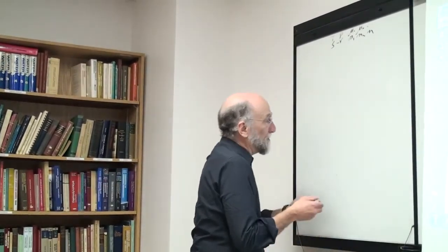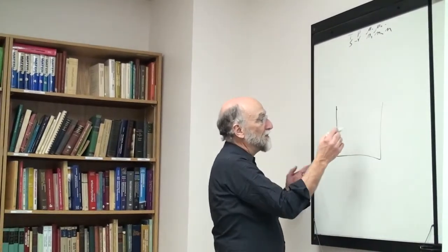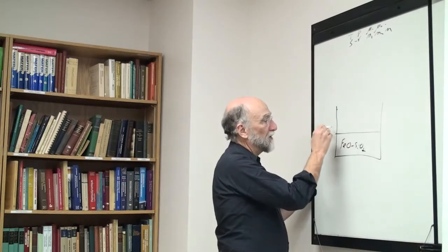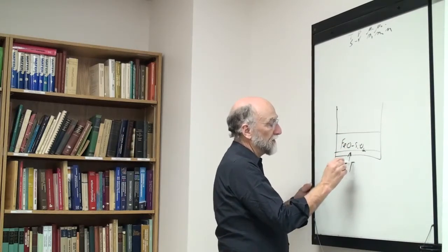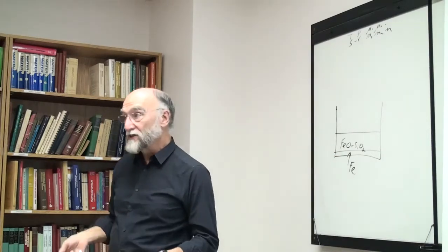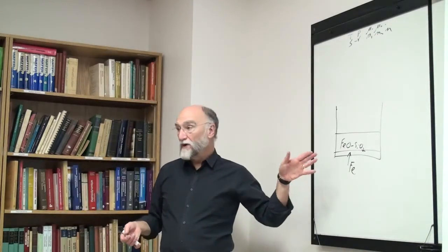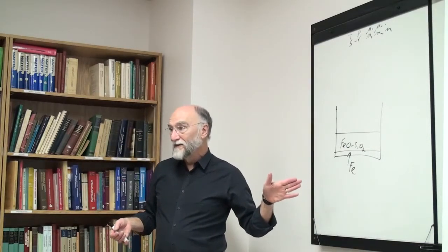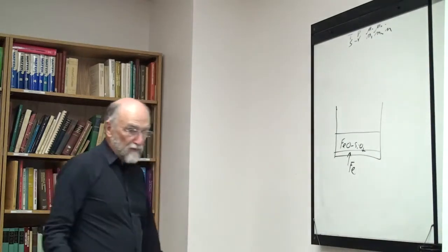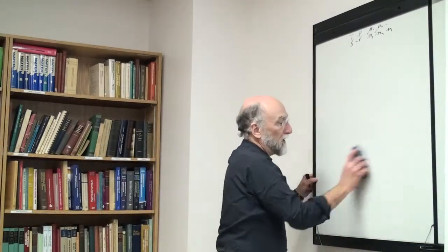So what you really imagine, this is somewhat similar to the previous diagram, but not exactly the same. Same idea. In this diagram, we're going to start with FeO and silica, and we're going to put it in equilibrium with Fe. Before we put it in equilibrium with oxygen, at a fixed oxygen activity of 0.21 atmospheres. Now we go the other way and we put it in equilibrium with iron. Okay, but now you can look at this, one way of looking at it would be, if the iron was in fact pure iron, I could do it the same way.